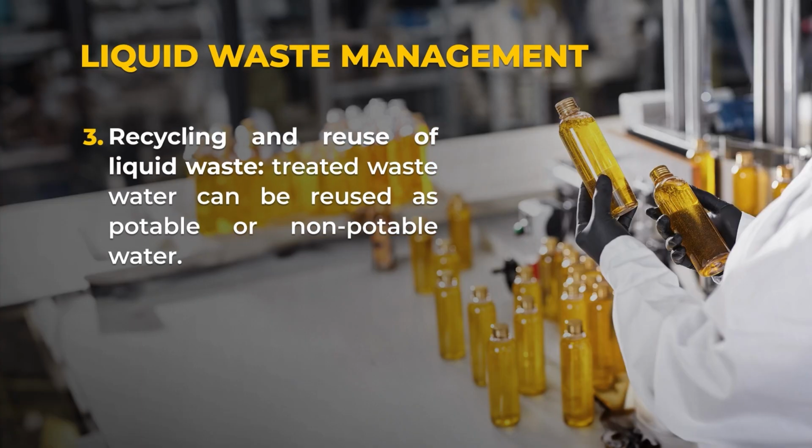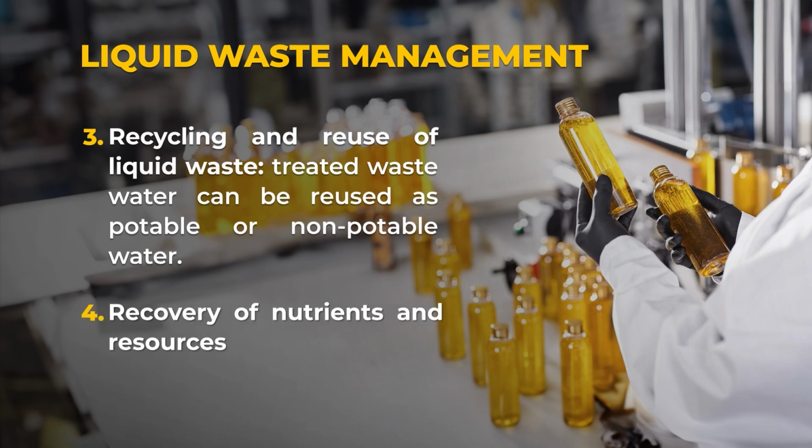So, treated wastewater can be reused as potable or non-potable water depending on the final quality of the treated wastewater. The wastewater can also be used for the recovery of nutrients, for example, recovery of nitrogen or phosphorus, and also for resource conservation, like we can also get biogas from the processing of the wastes.